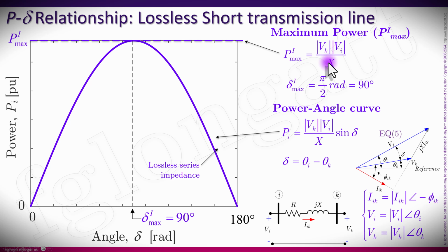A very important conclusion is that to control the active power in a transmission line, we can use the angle delta. However, modifying the angle delta is very complicated and difficult when we are working in multi-machine, highly interconnected transmission systems.